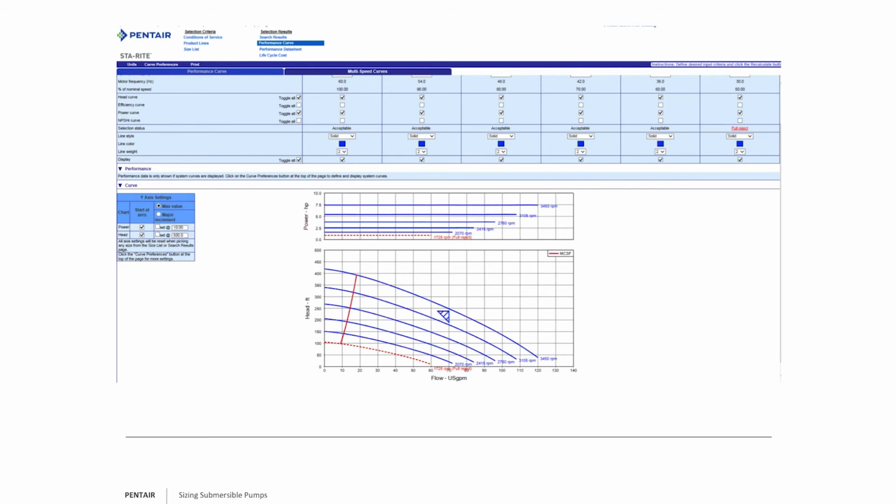It's because there's this golden rule of variable frequency drives that we don't go below 1800 RPM. If you look at this one, you notice the RPM on that red line is 1700 and some. It violates that rule. So that's where we want you to notice that. And one quick way to fix that is go up to that last one where it says the 1700, make it 1801 for RPM and hit recalculate, and now that line will turn blue again.